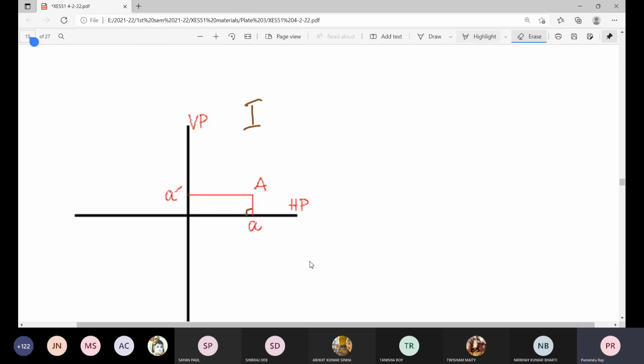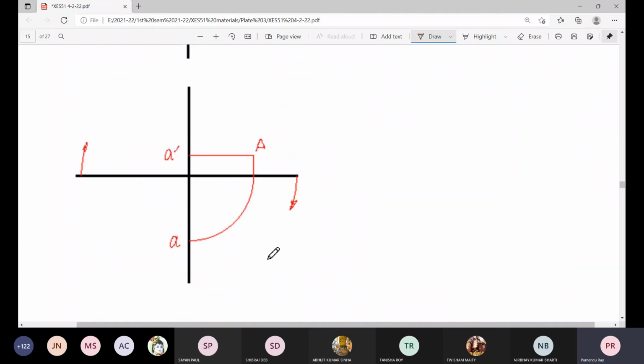Now next thing, the perpendicular projection on the vertical plane. This is the elevation or view from front or front view. Next thing, that formality: open the space so that the first quadrant is opened, and with this 90-degree rotation of the horizontal plane with reference to the XY line, this plane comes to join or overlap on this vertical plane.